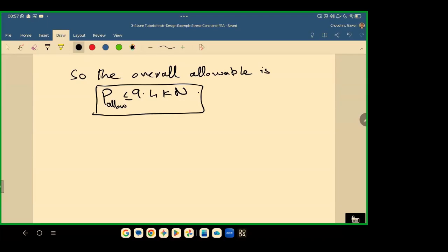Now, we can also evaluate the margin of safety for the bar, because for the pin, the margin of safety with this load will be approximately 1.5 anyway. We know, because that's how we have calculated, right? But we can reevaluate the margin of safety.